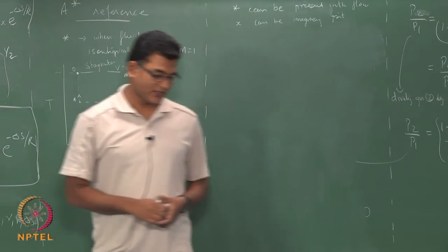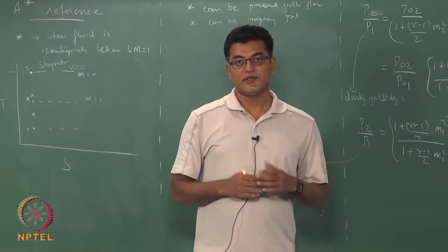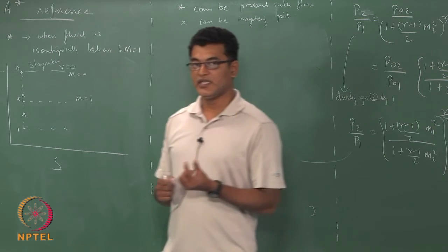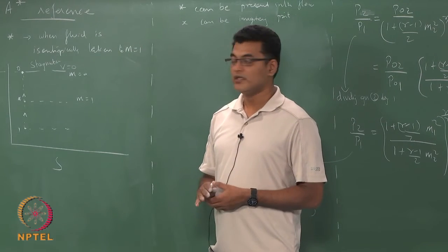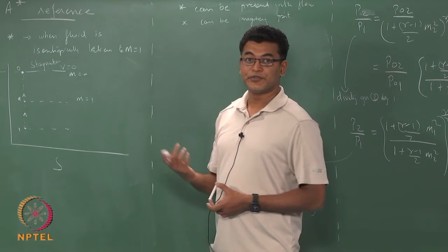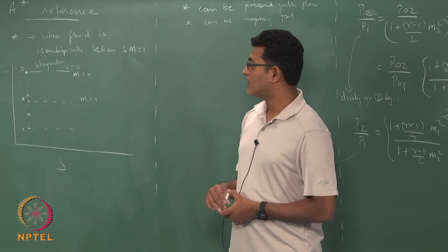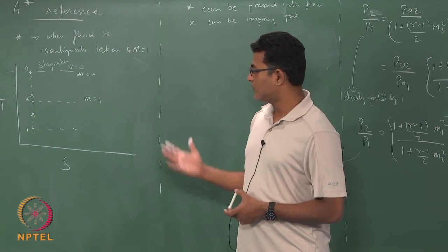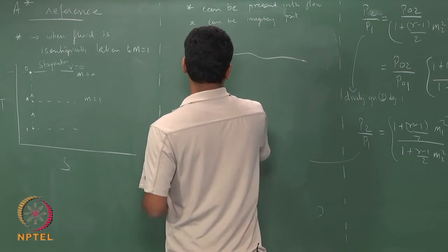Okay. So, if it is a converging diverging nozzle, your star condition is the throat area where your dA is going to be 0 and your M equals 1. So, that is also your star condition. We will come to that in a few lectures from now, but now let us concentrate on this arbitrarily shaped dA value.